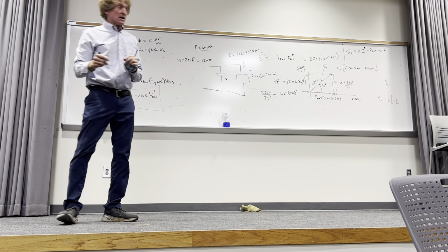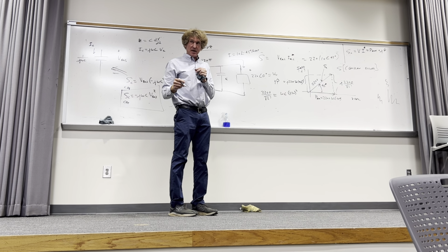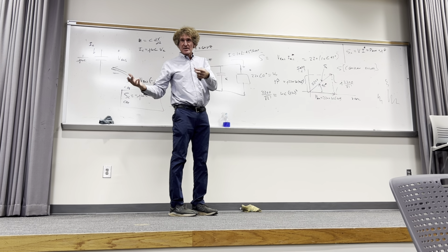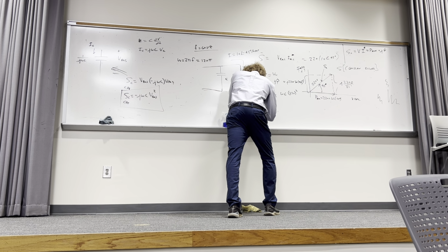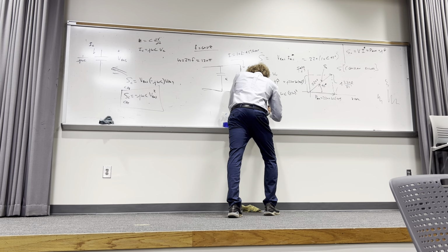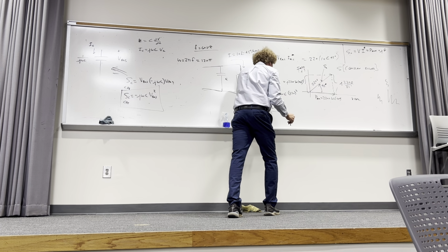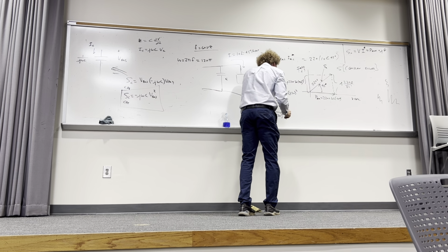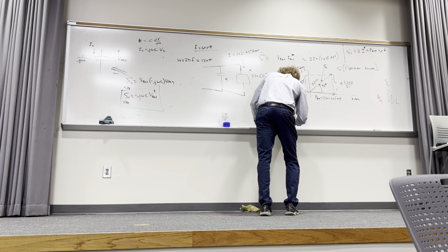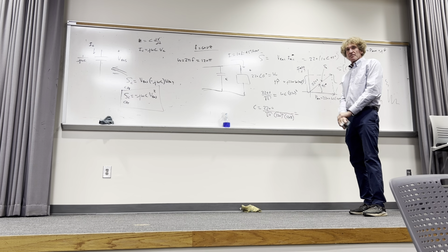With that in mind, now I'm going to calculate C. Everybody understand where the equation came from, right? Somebody's going to have to help me on this. C itself will be equal to 2200 over the square root of 2, divided by 220 squared, and then by omega, or 120 pi, to get a value of C. Would somebody be able to tell me what that is?